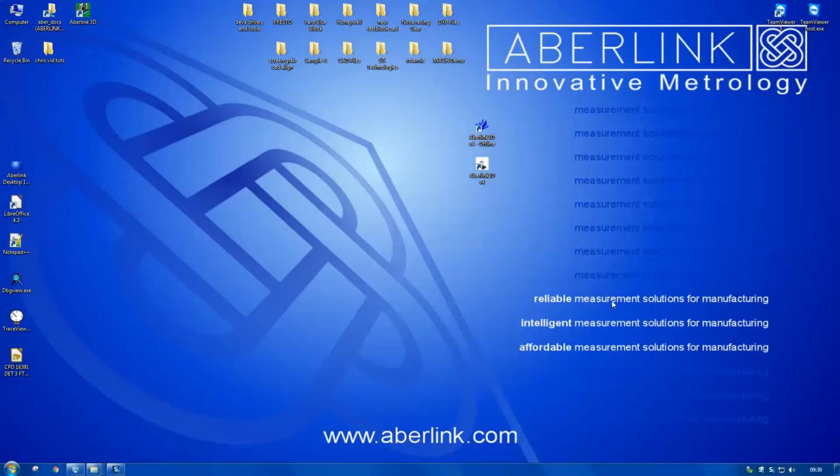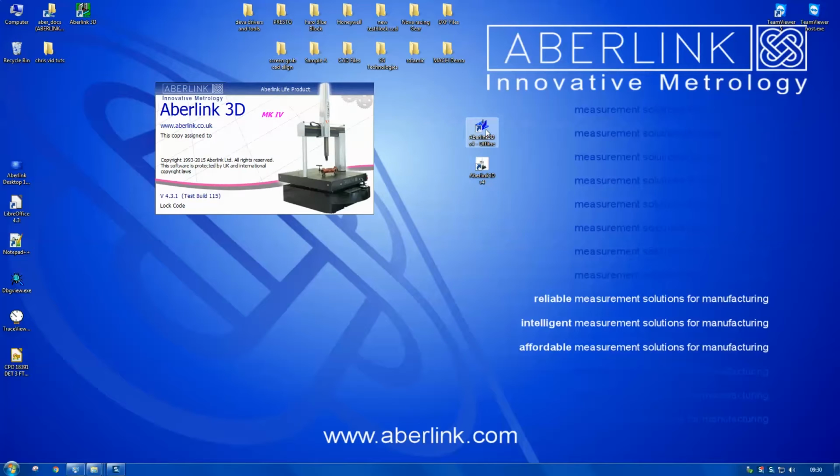Okay, first of all we're going to choose which icon to run from. You can see on the screen we have an Aberlink 3D V4 icon and an Aberlink 3D V4 offline icon. Now the Aberlink 3D V4 will try to start the machine and look for the various motion control devices. To program offline we need to choose the offline icon.